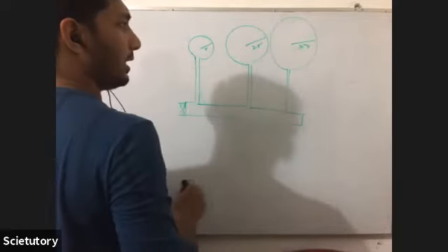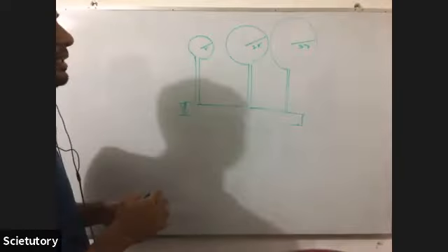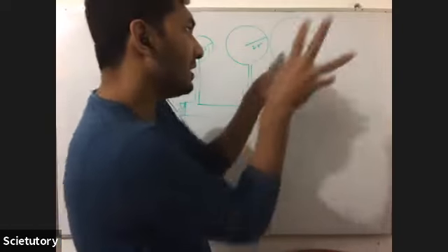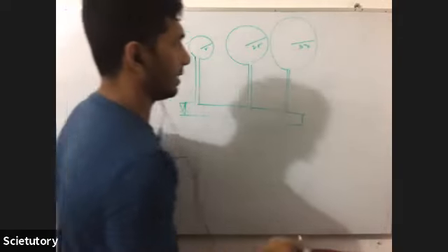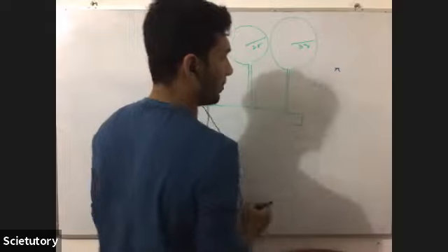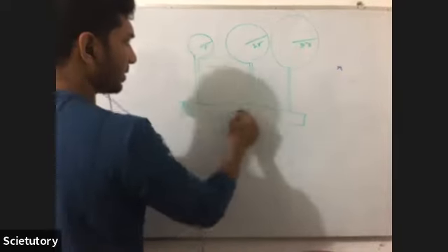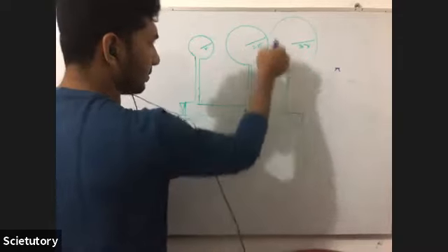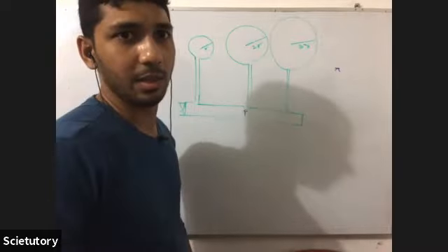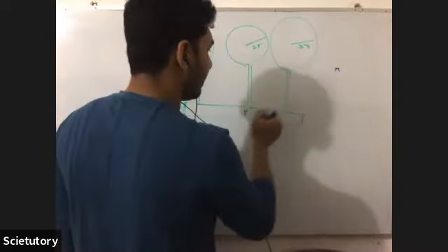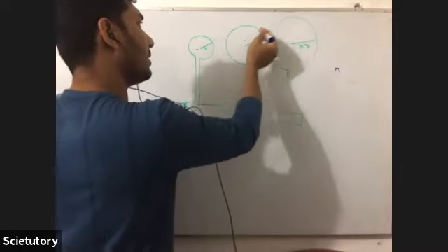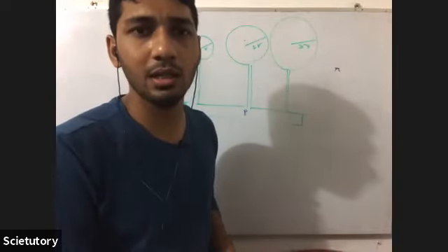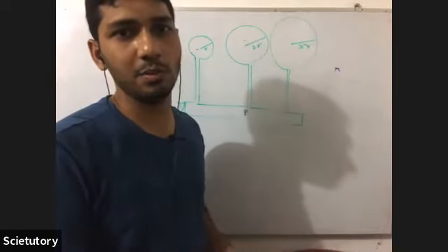So you actually have an increased pressure inside these bubbles. Why is that? Because they are bulging into the atmosphere. So they should have a higher pressure when compared to the atmospheric pressure. And also this system is continuous. You see? So there should be a constant pressure throughout all these areas. Am I correct? So the pressure difference across all these films, all these surfaces should be equal.